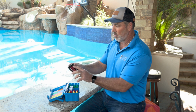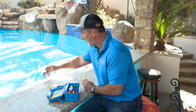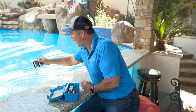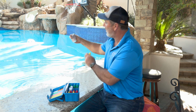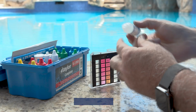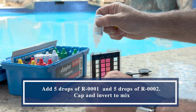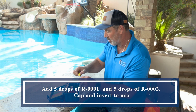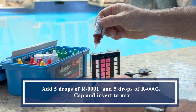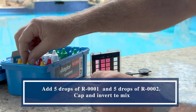First of all, I'm going to test chlorine and acid. Chlorine is the yellow drops. A lot of times you're going to want to get water about 12 inches below the water level, and I'm going to fill it to the line at the top, and then I add 5 drops of R1 and 5 drops of reagent 2, and I keep these in order.